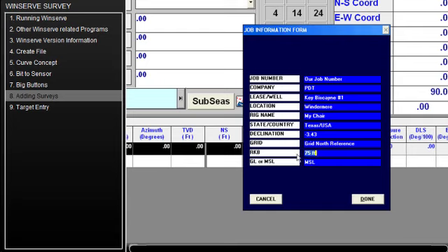For right now, this RKB that is stored here is only the RKB that you're going to have on your reports, and it can be representative of the total, as it is here, the total elevation above mean sea level, or it can be what it by definition is normally meant to be, which is the elevation that the rotary Kelly bushing is above the ground, but not necessarily including the ground elevation. But it's quite common practice to have RKB be not the elevation above the ground, but the total elevation above the datum, which is normally the mean sea level.